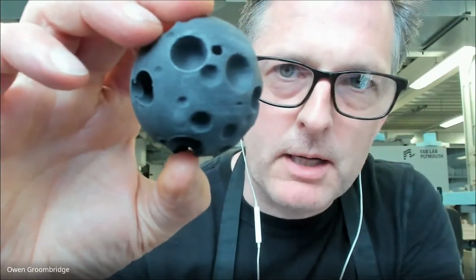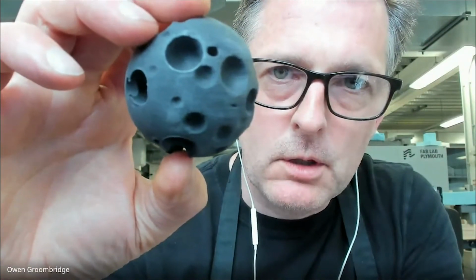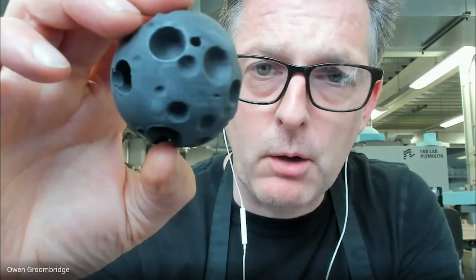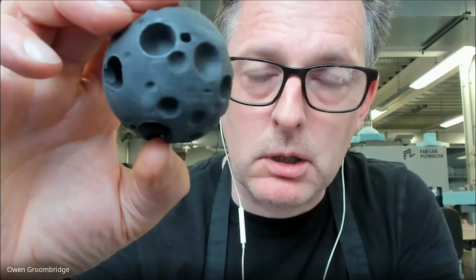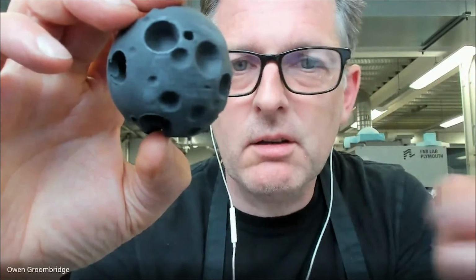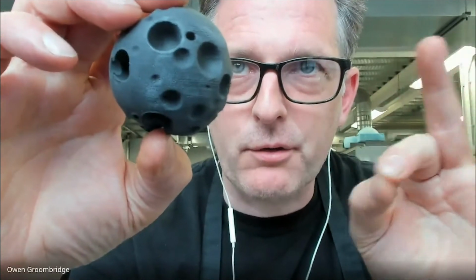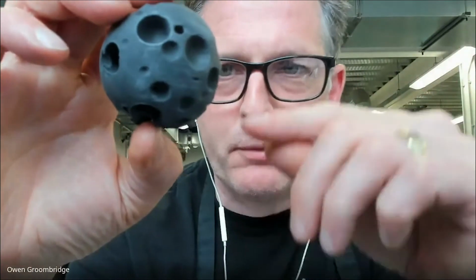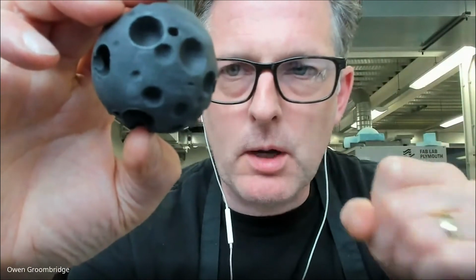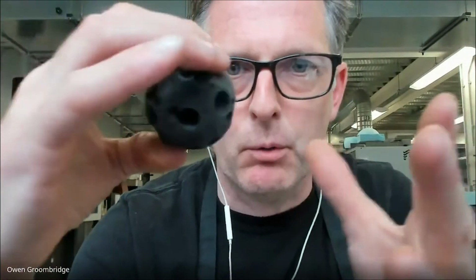This is made out of nylon powder, polyamide, and it uses a laser, and it lasers the parts that it needs to laser, in particular layers. Where that laser strikes this powder, it sinters it, it bonds it together. It's really hard. It's good stuff.